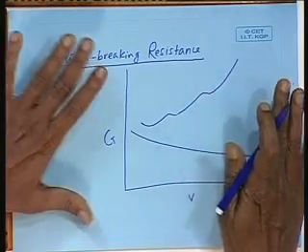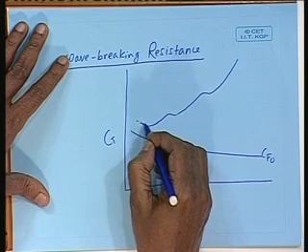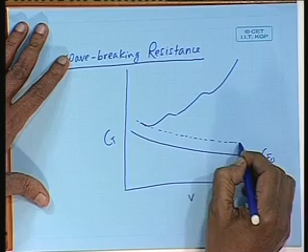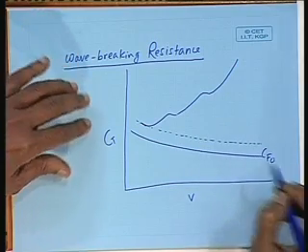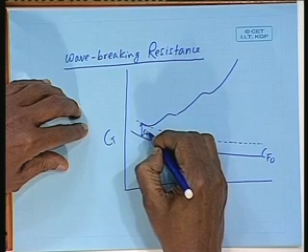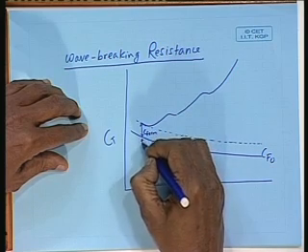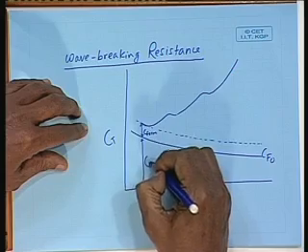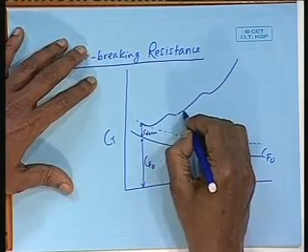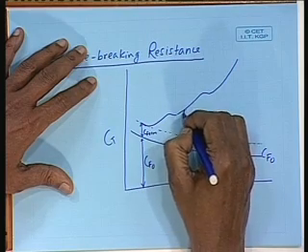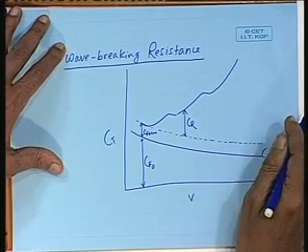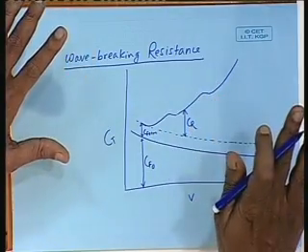This is what we have said, and therefore, we had said that when the wave resistance is 0, that CT, this we had called C form, right. Am I correct? And this then we had said as wave making resistance or CR, let me call it CR, and this CR was primarily wave making.